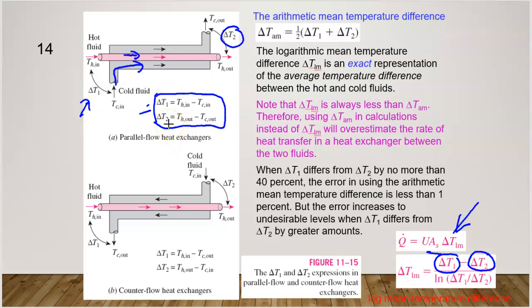Okay. So let's have a look at the difference in counter flow. What do we call counter flow? Counter flow is different flow direction between the cold and the hot fluids. Okay? So over here you see the cold fluids moving here, going there, and going here. So inside this shell, we have inner tubes. This inner tube we have a hot fluid. Maybe this one is water, maybe this one is refrigerants, right? So this one is counter flow.